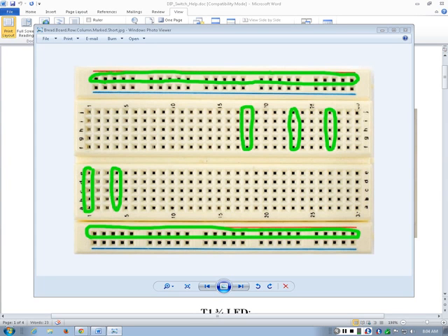Just again, before we move on to the next image, on any breadboard all these columns are short, but remember these points are not short. This block is not short with this, but in this block all the columns are short. In this block these 2 rows are short. Look at how we mark the green ones. Similarly, this row is short as well. The top 2 rows are short. Short means they are basically the same point, but you have a bunch of holes so that you can extend your wire and connect them.